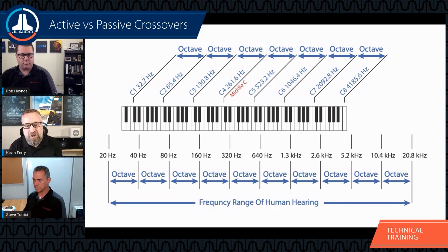So you can see up here on the chart, we have 20 hertz to 40 hertz. That is one octave. We've doubled that 20 hertz. 40 to 80, 80 to 160, 320 to 640. Now you could take 500 to 250. That is also considered an octave, even though it's not on the screen. It's a halving of your given frequencies. So when you hear that utilized, when we're talking about 24 dB per octave, we're talking about that halving or doubling of a given frequency range.